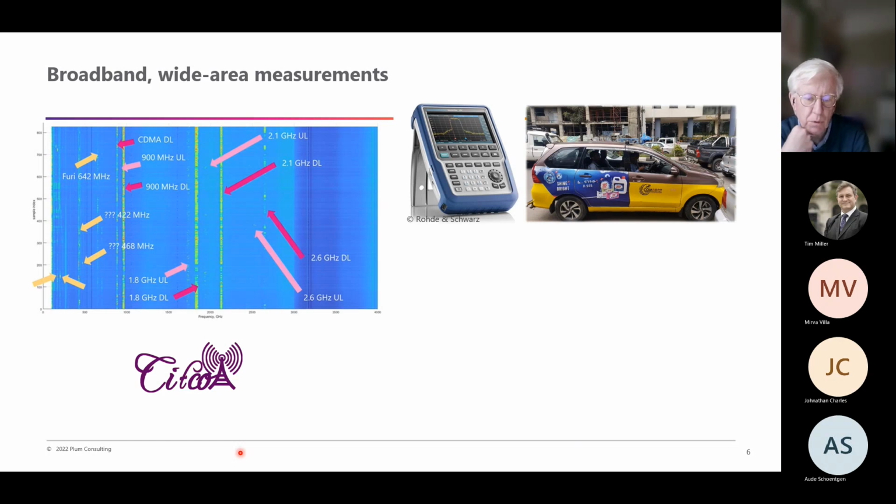So there comes a point probably around about 4 gigahertz where it gets very hard to make meaningful mobile surveys of this kind, just because to detect signals over a useful range requires highly directional and higher gain antennas to dig down into the noise to understand what sort of signals are out there.